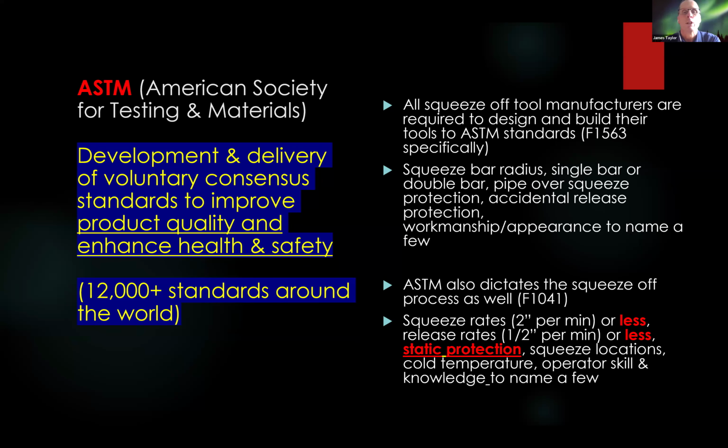So we talk about squeeze rates. They say 2 inches per minute or less. Release rates, 1/2 inch a minute or less. Static protection, why we're here today. Squeeze locations: you can't squeeze at or near a joint, it must be 3 times the pipe diameter away from a joint. Cold pipe, cold temperature, we touched on that a minute ago: anything below 32, you have to extend your time or double it. Operator skill and knowledge are required too, per ASTM, to operate a squeeze-off tool and be familiar with it. Those are two standards: squeeze-off manufacture under F1563, and then 1041, how they're used in the field.